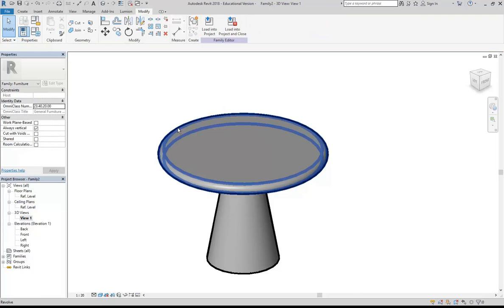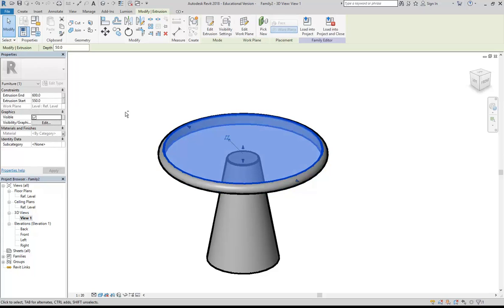Now I'm going to select the original tabletop. It's not coming up when I go to click on it, so I'm going to use tab, pressing it twice, or, oh no, it's all right. Sorry, I did want to show you this. You don't have to do it, because it was joined, it's already assigned it anyway. So over here you can see associate family parameter. That button there has the two lines on it, which means it's already got a parameter.